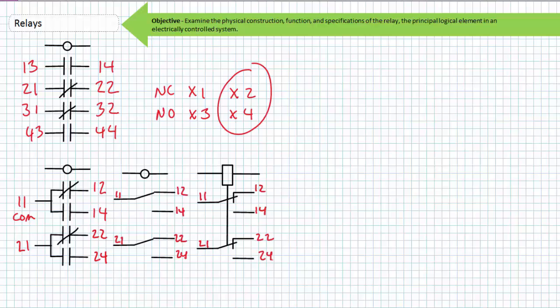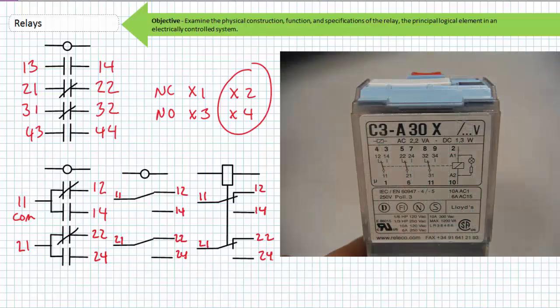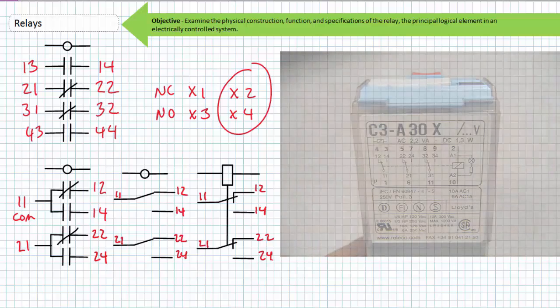Alternate representations of the schematic would use the same terminal numbers. Any additional switches associated with this relay would continue in the same fashion, starting at 3 for the first digit. If you're ever lost about which pin is which, just look at the manufacturer's datasheet or on the side of the relay itself. Very often the pinouts are printed on the side as well as pertinent electrical data.